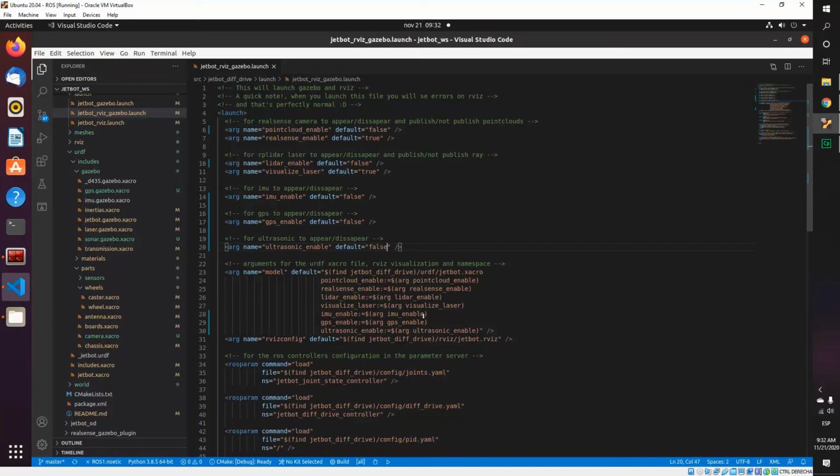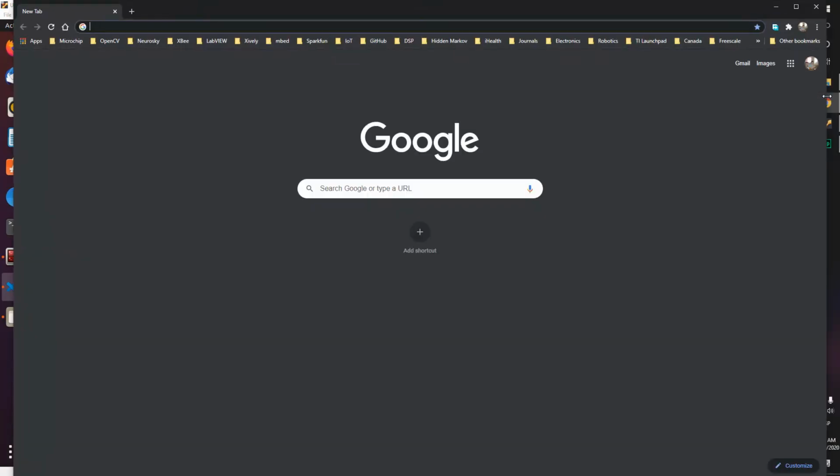In the end the drifting is caused by the physical configuration of Gazebo, and that is caused by your URDF model. You have to check the collisions, you have to check the center of mass or center of gravity, I don't know how to say it. You have to check your inertias. There is a good reference, I think in Wikipedia.